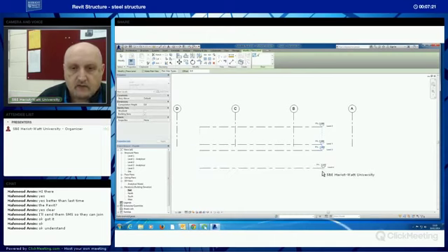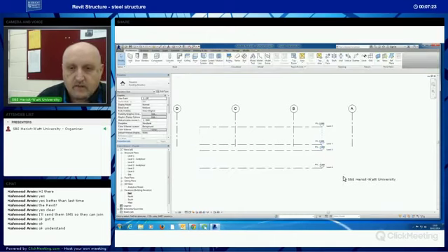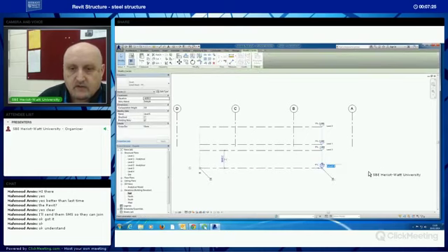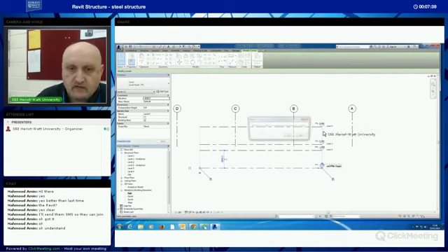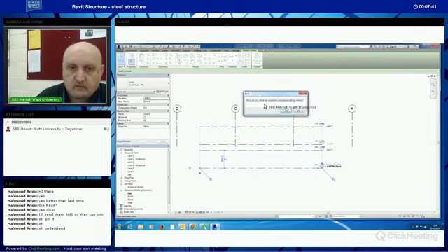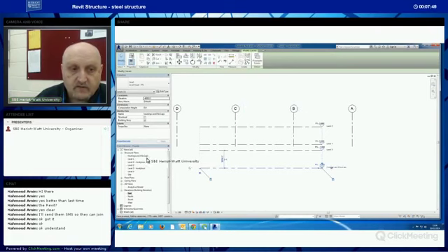So that's going to be 2 down there. Now this one here, I'm going to call it the deep level foundation. I'm going to call it footings and pile caps, which is what's going to be on it. Footing and pile caps. I just click in the white space. I get this usual dialog opening up saying would I like to rename the corresponding views, and that's going to be a yes, and this will rename it over here. That will become footings and pile caps.